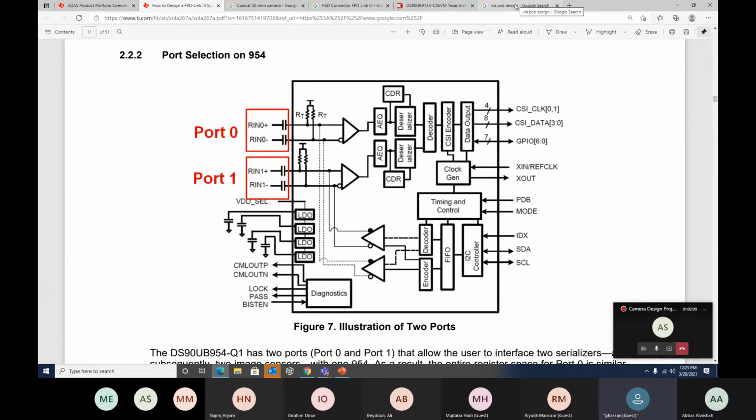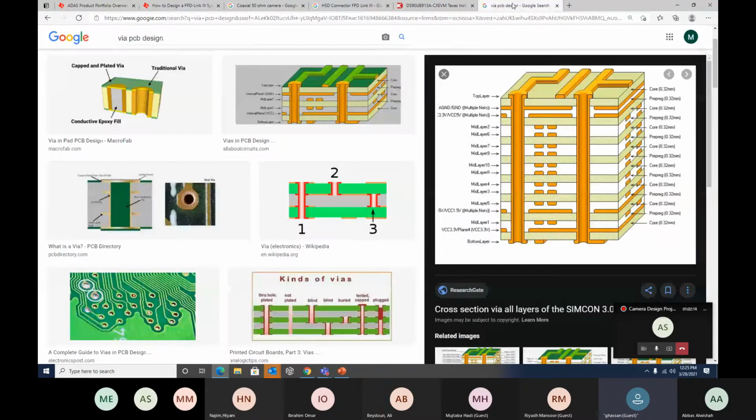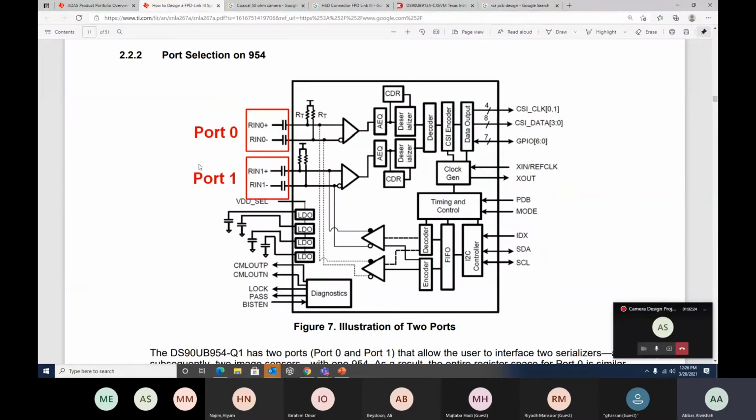So I need to check the error at each point through the layers, so you know where exactly you have something wrong. Exactly, you said it. If we have an error. But if we don't have an error, that's good. But if we had the right input and something here doesn't look right with the clock, then we can go back and measure and say the value between here and the input should be this much. Is it a decoder problem? Is it a deserializer problem? Which one is it? And then we're able to figure it out.